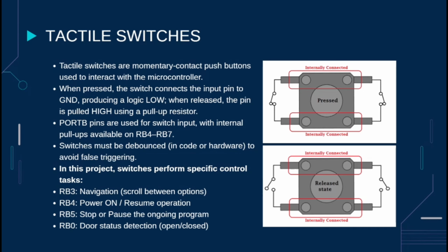Next up, tactile switches. Tactile switches are small push buttons that are used to take user input. When pressed, they connect the microcontroller's input pin to ground, and when released, the pin is pulled high again. And port B pins are used for switch inputs. So in this project, 4 switches are used.